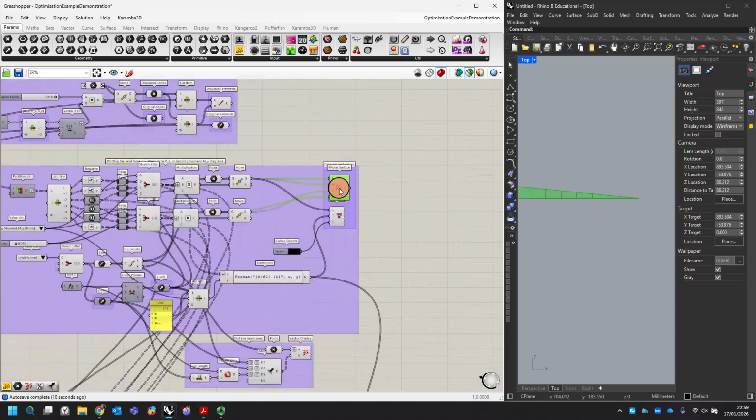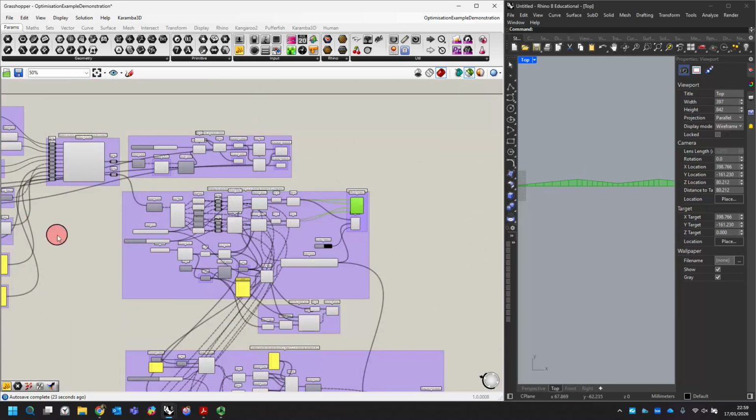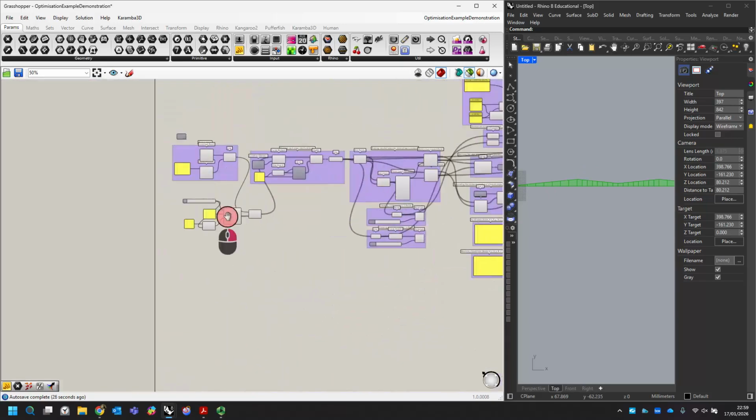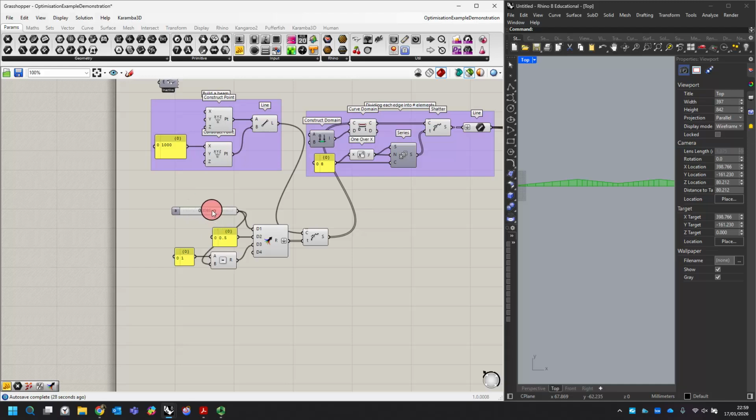Okay, so what we can now look at, I hope, is if I come along and I just look at my bending moment diagram, so we can see actually the form of it is such at the moment the bending moment is positive the entire way along, and hopefully I'll be able to get back to my slider. So as I alter the position of that slider, you can see that affects the magnitude.